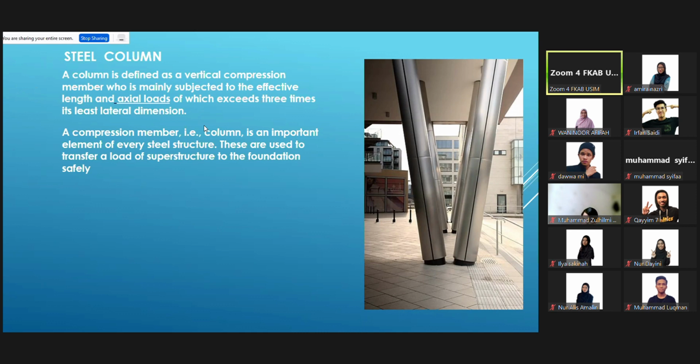But as an alternative to column, you can design the building without column, which is what we call load-bearing wall. In a load-bearing wall, basically the whole wall, less all the openings, the doors and windows, is taking the load from above. Of course, they have some limitations. They cannot go up to 5-6 floors. 2-3 floors is okay.